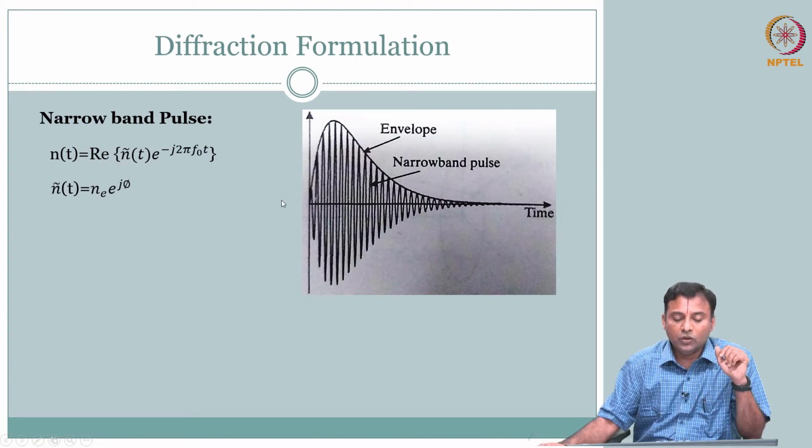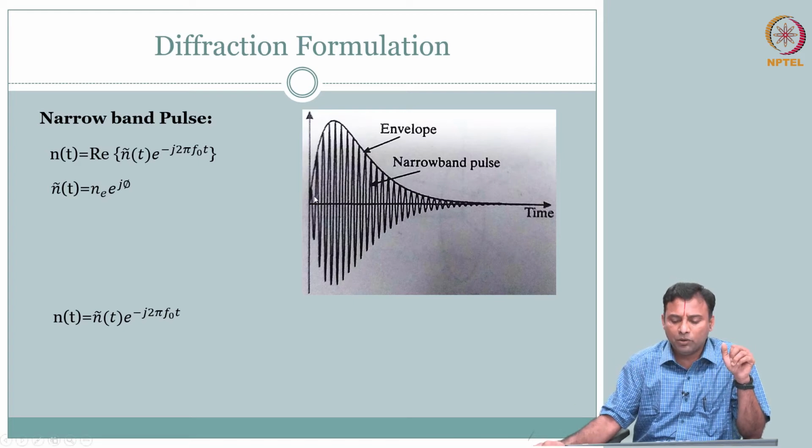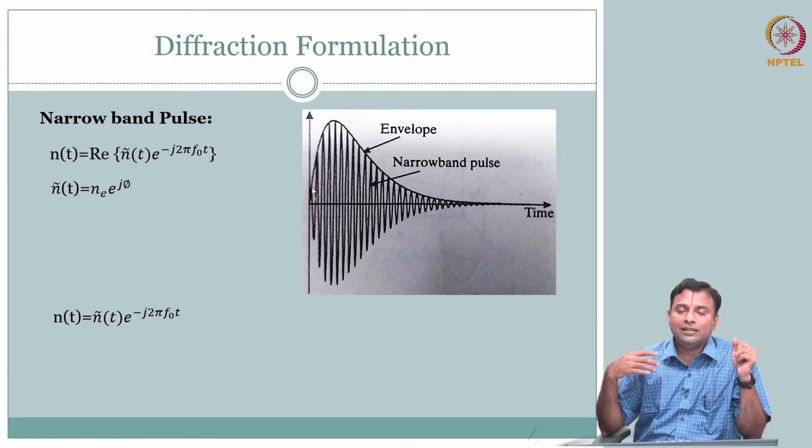Okay. So, we will take this. Typically what happens is we send about 3-4 cycles of this, say for example a Gaussian modulated sine wave with 3 or 4 cycles is a typical pulse form that is sent in for your pulse echo imaging.